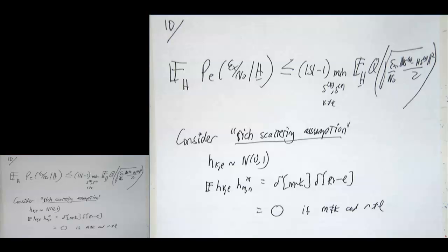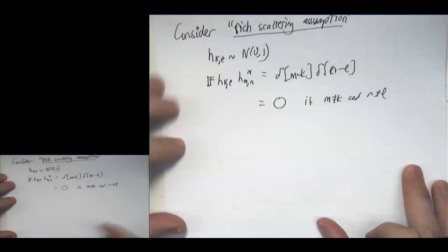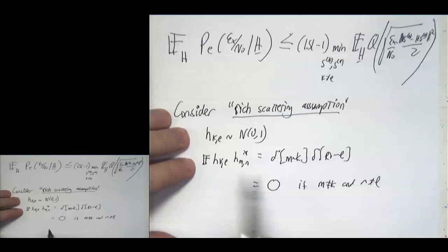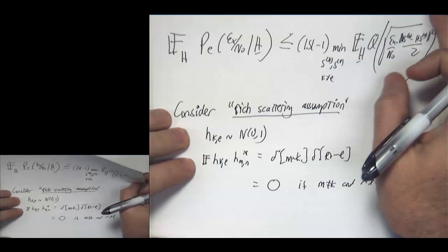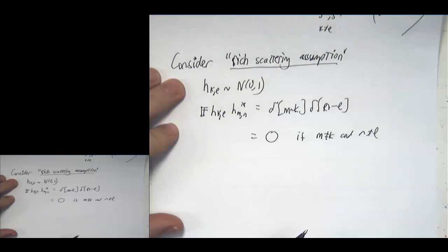Okay, so with that assumption, now, that's also the same assumption we made for analyzing the performance with maximum ratio combining and with the Alamouti scheme. The only difference here is that we've now generalized it to multiple transmit and multiple receive antennas. Now, the other kind of tricky new piece of information we need here is that we have a matrix channel now. Before we started with a scalar, then we went to a vector, now we have a matrix.